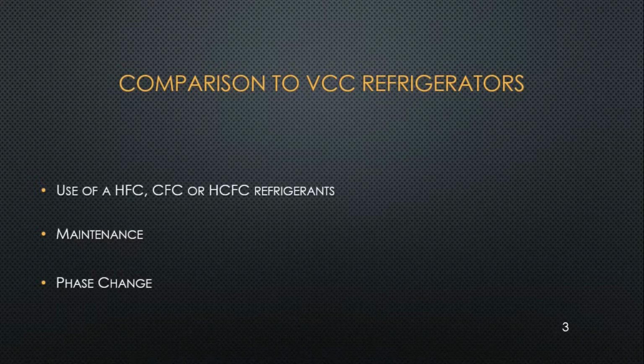A lot of moving parts are involved in vapor compression cycle refrigerators, while in standing wave thermoacoustic refrigerators, except the sound source, there is nothing that has to be moved. Phase change does not occur in thermoacoustic refrigerators. In vapor compression cycle refrigerators, it occurs. Now it is a good process. It allows a lot of exchange of heat. Maximum exchange of heat occurs by the phase change, where there is no change of temperature, but there happens a change in the state of the fluid.